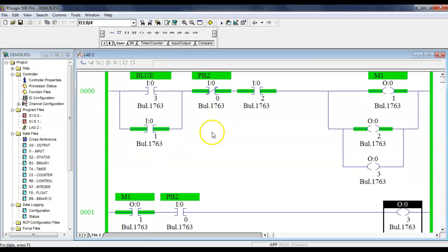And the way the PLC scans, it reads inputs, runs logic, updates outputs, reads inputs. And the problem is this one is down below that one. So here's output 3, there's output 3. This rung is telling output 3 to turn off. This rung's telling output 3 to turn on. But since this is down at a rung that scanned last, it's the one that takes precedence.